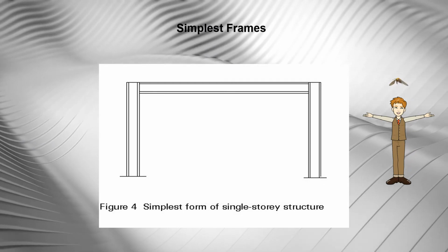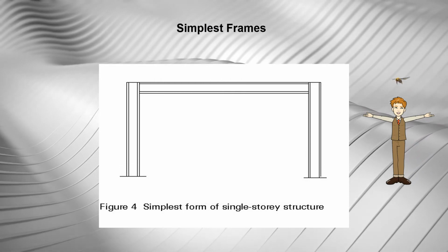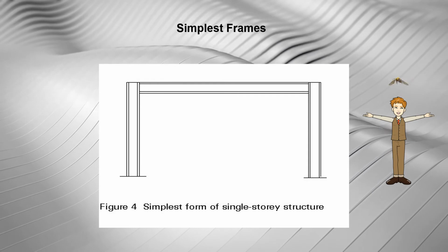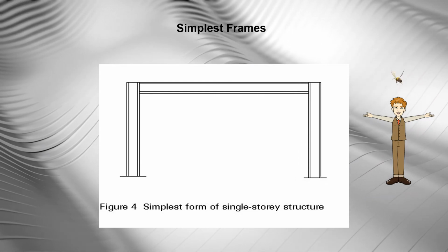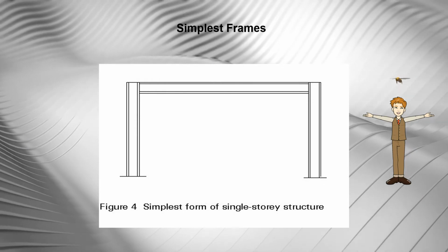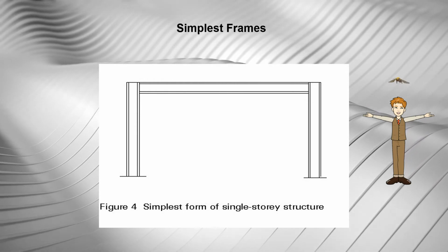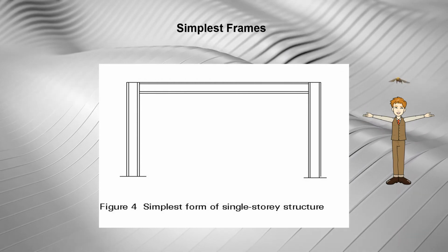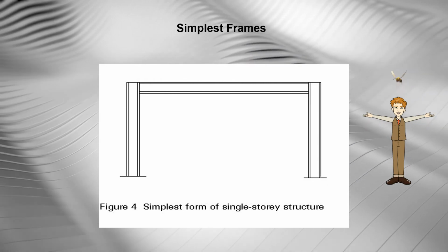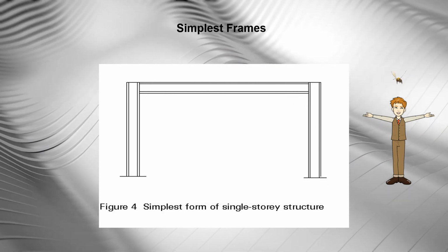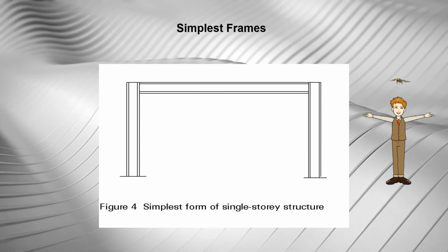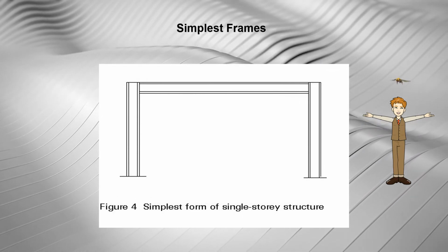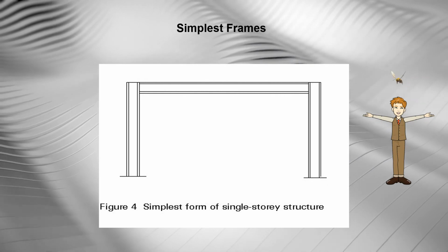Resistance to lateral load is achieved by the use of a longitudinal wind girder, usually situated within the depth of the crossbeam. This transmits load from the top of the column to bracing in the vertical plane and hence to the foundation. The bracing is generally designed as a pin-jointed frame, in keeping with the simple joint used in the main frame.